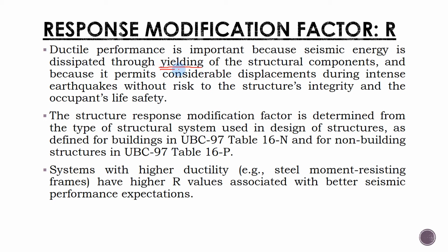Okay, the meaning of yielding, guys, is the ability of the material to elongate or deform, but it does not return to its original form. Okay, once it yields, guys, there will be considerable displacements, which the occupants can immediately see, that the structure is deforming or displacing, so at least there is an early warning. Okay, so that is as stated earlier in the ductility part.